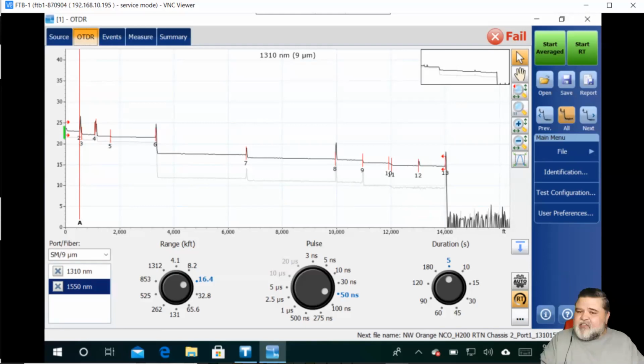We're starting to see a shift towards 1625 as well, particularly for hyperscale customers, your big single data center customers like an Amazon or a Google that are starting to require 1625. We're seeing it with ultra long haul, of course. And now we're seeing a lot of DWDM. DWDM is being pushed further and further into the access side. So now contractors that were typically just running drops or wiring radios are now dealing with fibers that carry higher capacity, which was typically relegated to the long distance world.